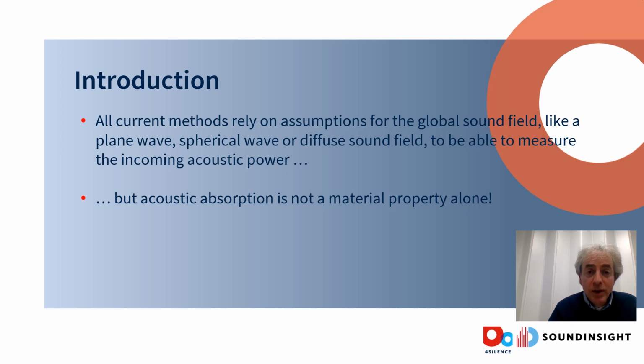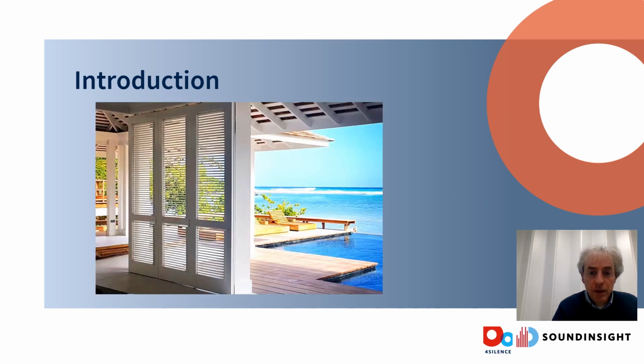But my statement is always that the actual absorption of an absorber depends not only on the absorber, but it also depends on the sound field that is impinging onto the absorber. So it actually depends on the in-situ sound field. To illustrate what I mean, let's take a look at an example. And the example I have in mind is a louver door. So here it's shown in the picture.